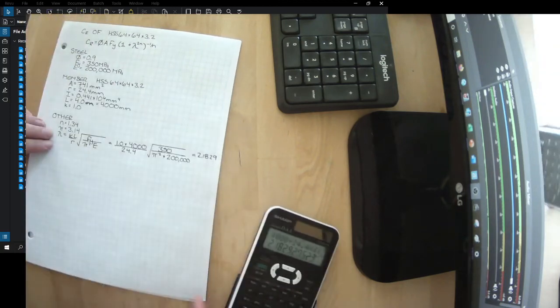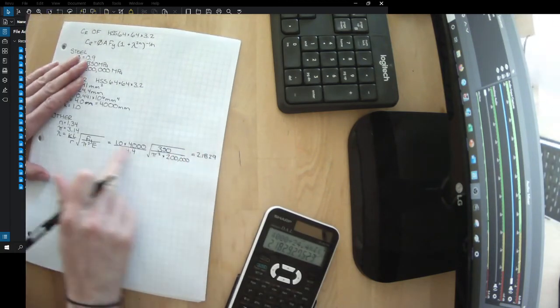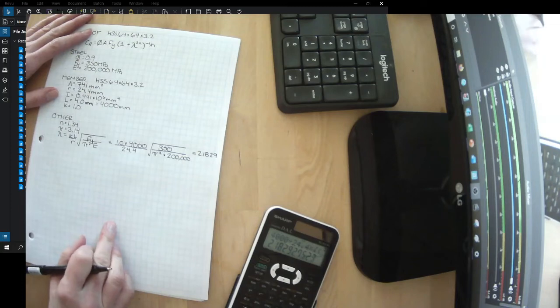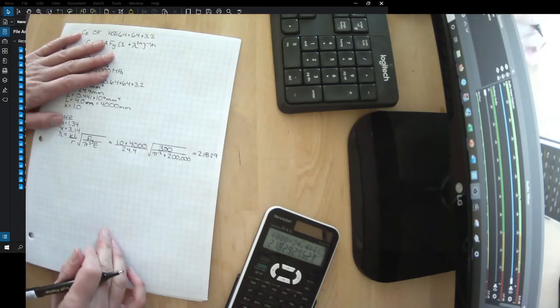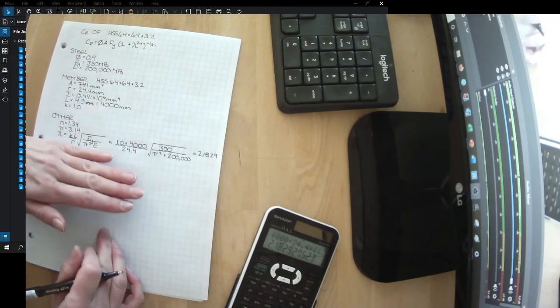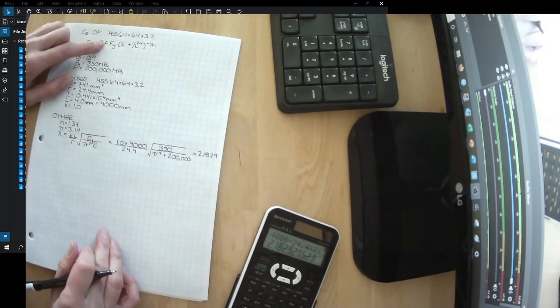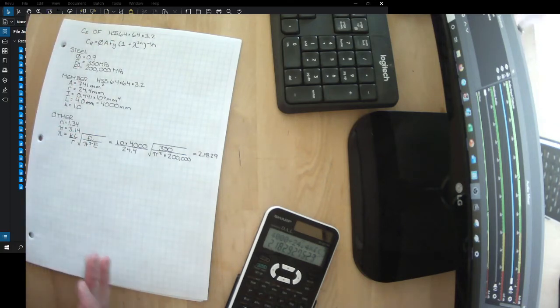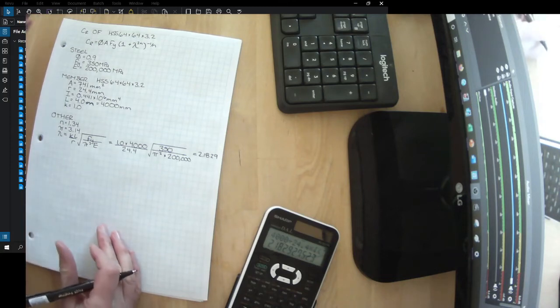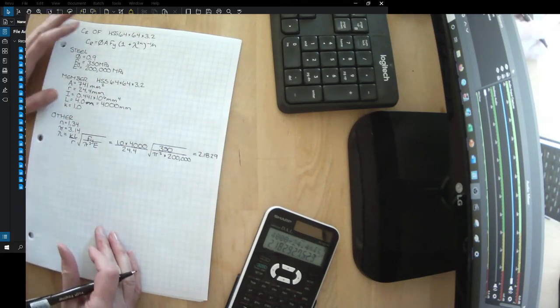So we've got a lambda now. We've calculated lambda. We know that this has something to do with critical buckling. And critical buckling governs the design of a column if it's really tall. Squashing, this part of the equation, governs it if it's really short. We don't know what really tall and what really short means, but it's somewhere in between there.